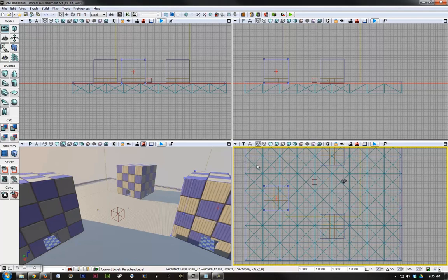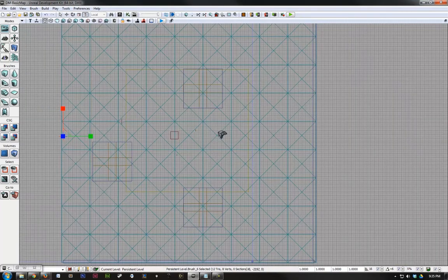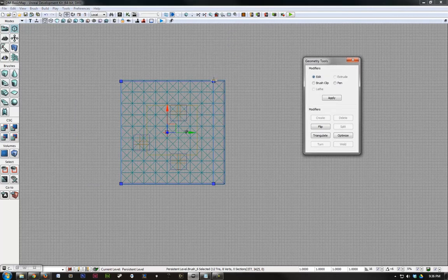To do that, we're going to take one of our walls here. So I'm going to go in the top view. I'm going to select this, and then I'm going to go to the non-uniform scaling and just scale it out a little bit until it looks about the right size. And then I'm going to line it up. Then go into our edit geometry mode like I explained last time and grab these vertices here and these ones here. And then I'm going to set the orientation to world and drag it so that it finishes up our square area.